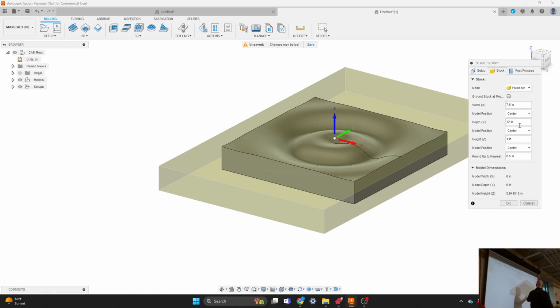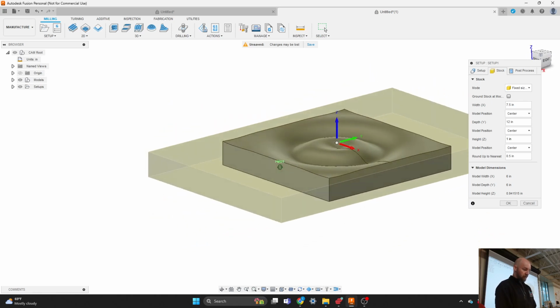Keep in mind that if you're using a 1/4 of an inch tool to cut this out, now you don't have 3/4 of an inch extra space. You only have a 1/2 inch extra space because your tool's got to fit in there, right? But we've got 12 inches on either side here, so I can put my clamps down here, and that'll be just fine. So there's some thought that gets put into our stock and measuring it and having it right.